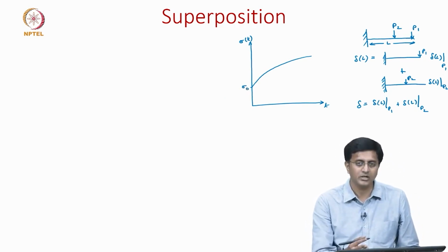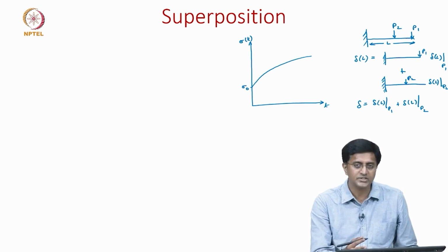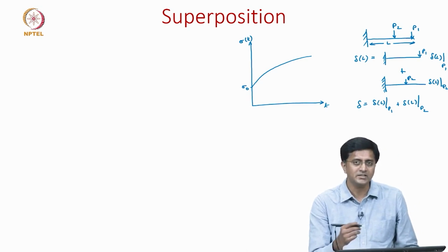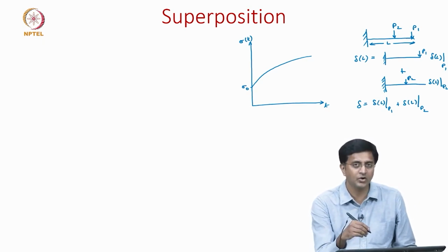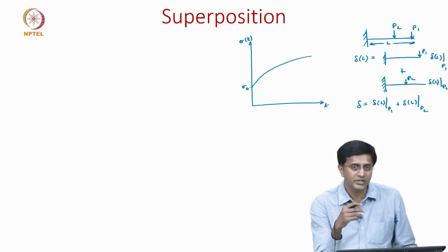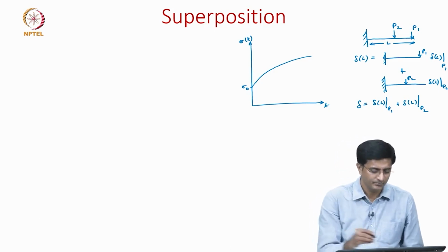So, we can represent this nonlinear load input as a series of step functions. In this case, since the load is the stress, we will consider these step functions as creep loads, because in creep the input is constant stress.